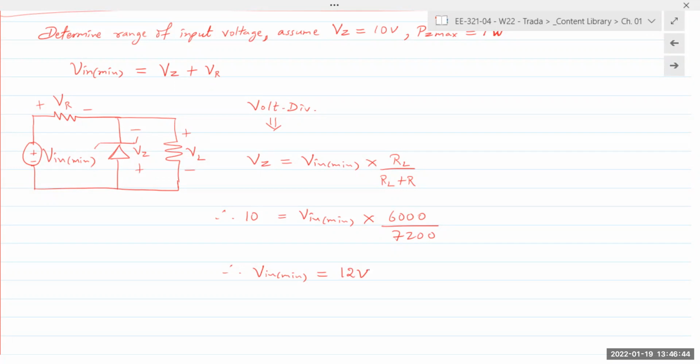Then I would think of the adapters that I'm using, this adapter right here. It is also simply taking AC voltage and rectifying it into DC, but it has a lot of other extra protections built into it, like current protection and over voltage protection. If my laptop requires 19 volts, the output should stay at 19 volts, so I would have a Zener diode of 19 volts to regulate that voltage.